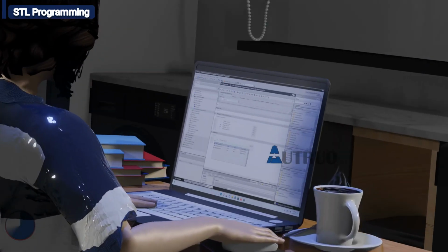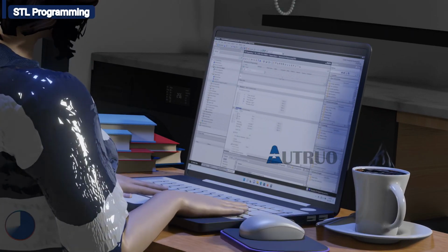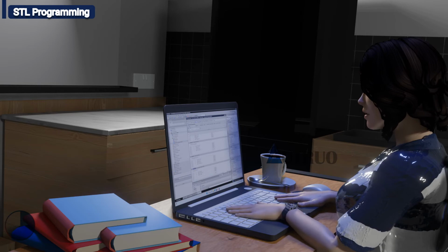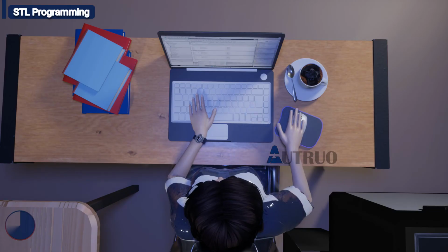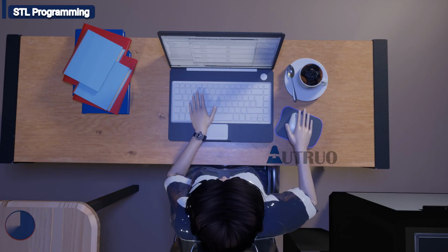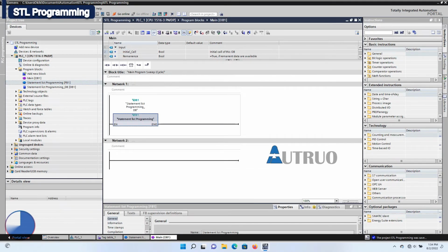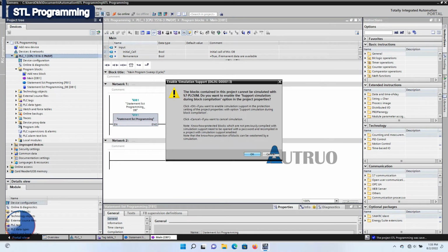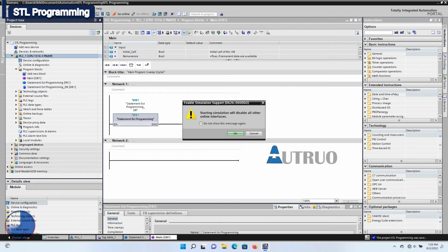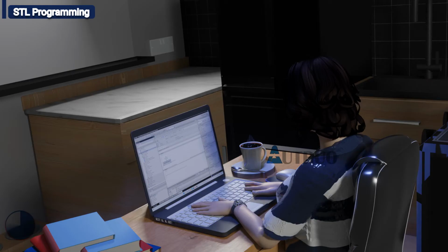Just like what was discussed earlier in the first network. The normally close of the contact references these. And it depends on these conditions, and the overall system also depends on it as well. Now, I will drag this block to OB1 for program calling. Likewise, I will also download this code to our simulator and let's see how it will work.